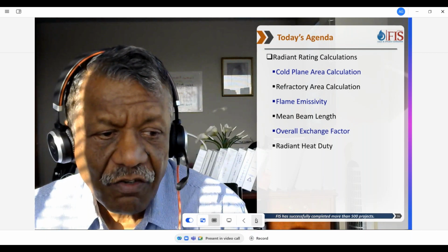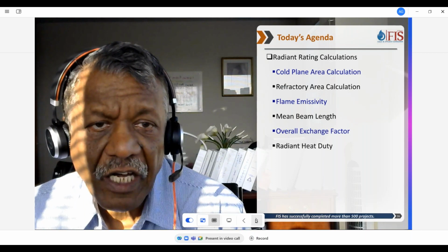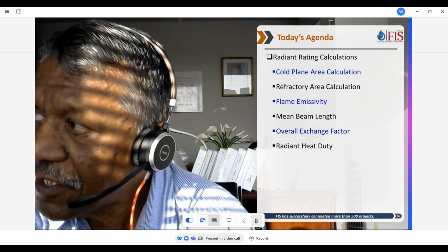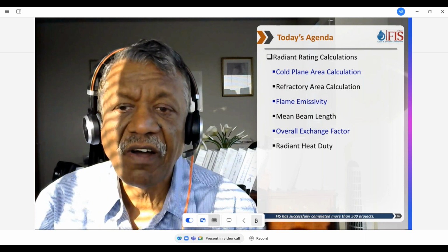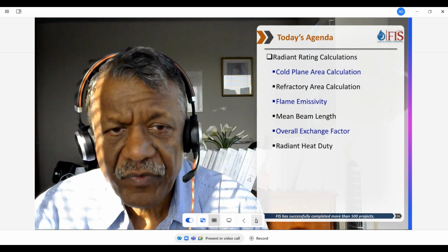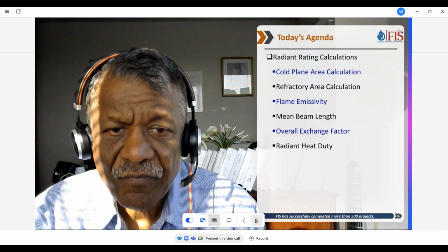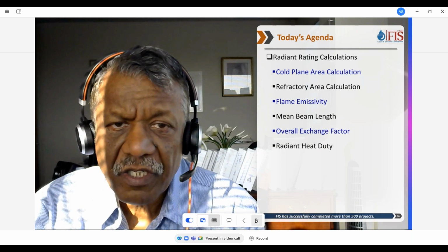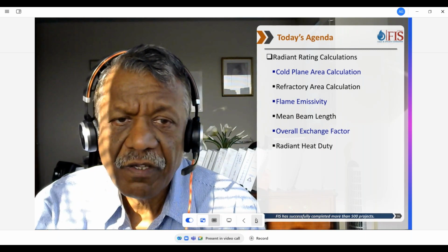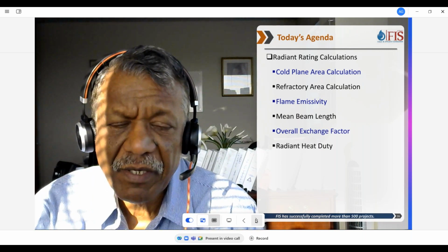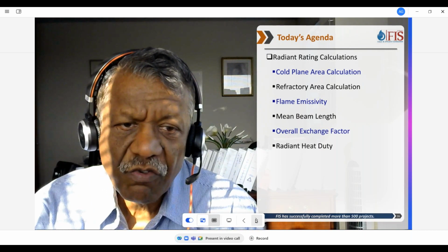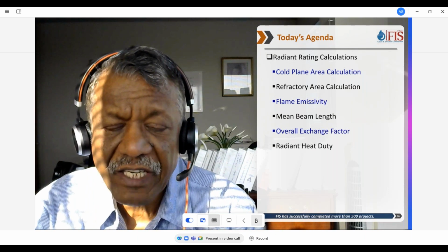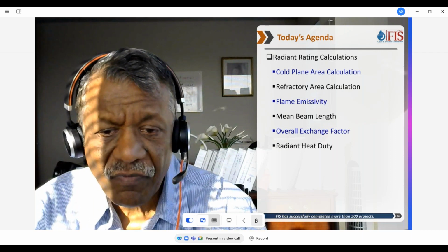So today, what we will be talking about is how we do the radiant section calculations. I did some of it last time, but I think it was done very fast. So we are going to go slow and go step by step today so that you can all understand it. We'll talk about cold plane area calculations, refractory area calculations, flame emissivity, mean beam length, overall exchange factor, and radiant heat duty calculations. So this is what we will be doing today.